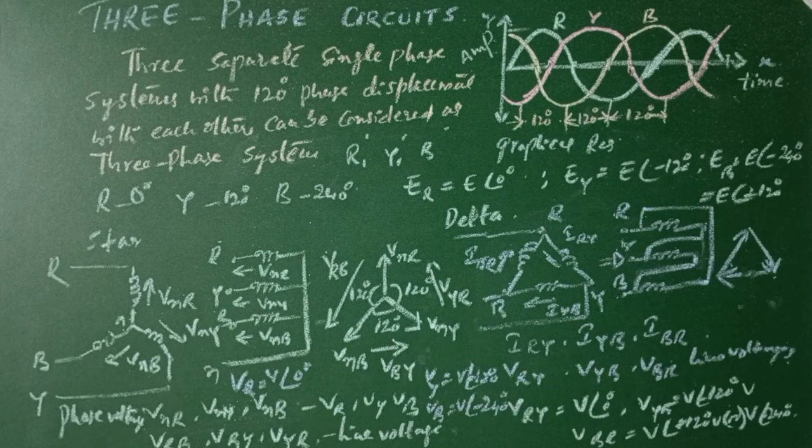with the three-phase system. Now, when you consider the technical aspects, the voltage regulation of the three-phase system is better than a single-phase system. Three-phase induction motors are self-starting while single-phase motors are not. So, three-phase system clearly has the advantages over the single-phase system. Torque produced by a three-phase motor is more. For the same size of frame, three-phase generator provides more output. So these are the advantages of three-phase system over single-phase system.